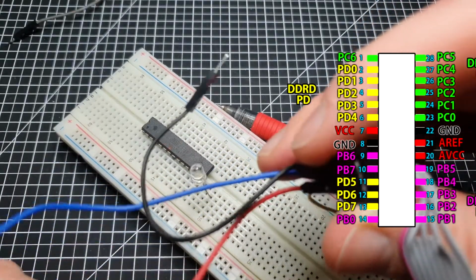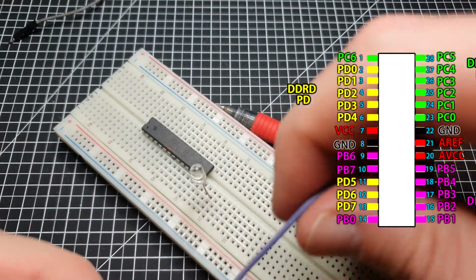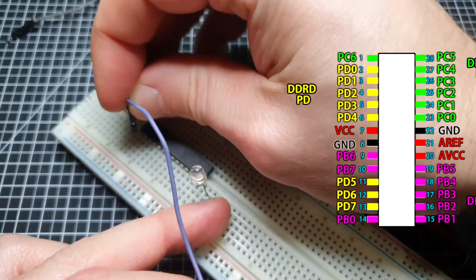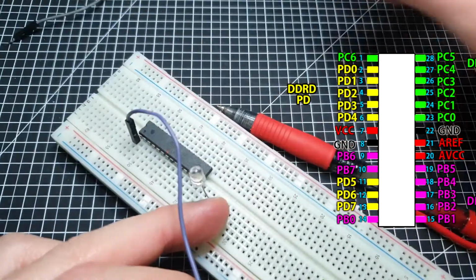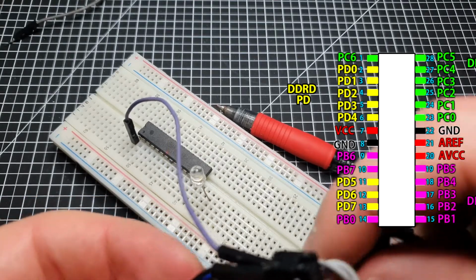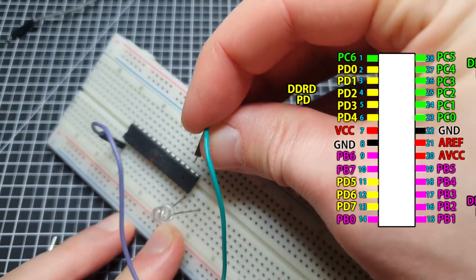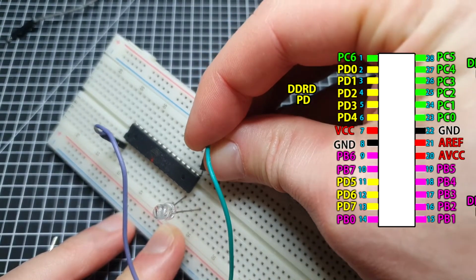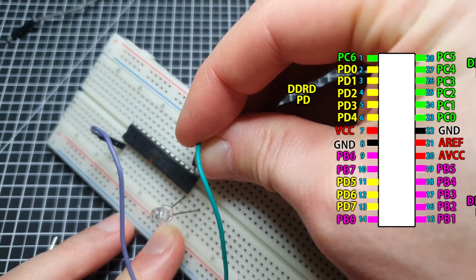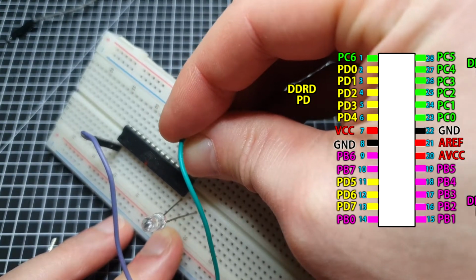So we have our LED set up, and we need to put in our reset in the top left. Boom, just like that. And then we need to put in our SCK. So I just count up, this is the easiest way to do it. I just count up 2 from the bottom, and then these 3 are going to get 3 wires.